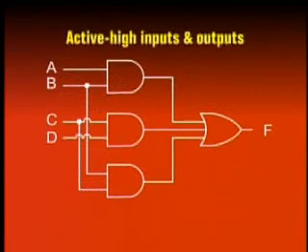The simplified sum of product based implementation has an active high output. The circuit can be implemented to have an active low output by connecting a NOT gate at the output of the circuit. Now, whenever adjacent ones are detected, the circuit output is set to 0. The circuit is also shown to have active high inputs. The circuit can work with active low inputs, producing an active high output if NOT gates are connected to the inputs of all the AND gates.